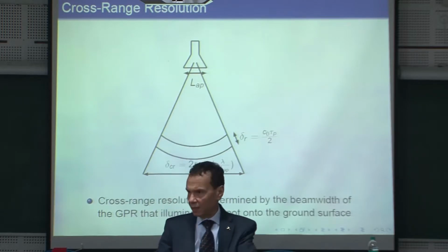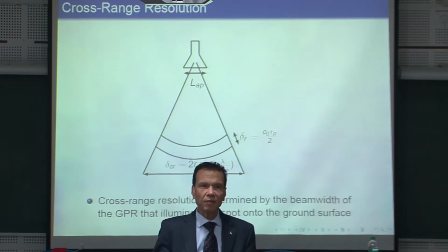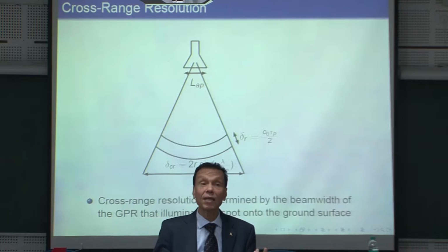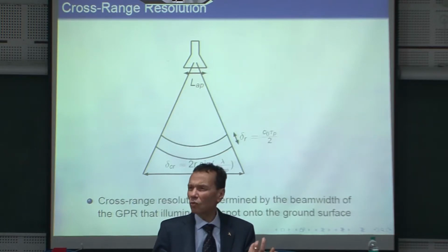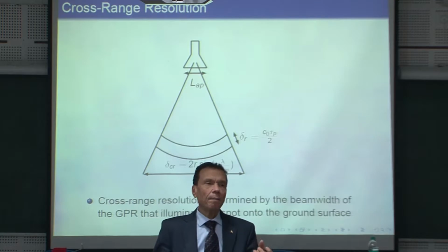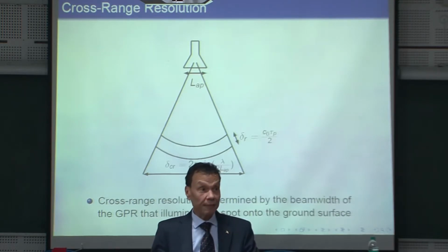Let me refresh your information: for the array factor, we assume that your unit antenna is isotropic, as if it were a point source or point receiver. But don't forget that you multiply the array factor by the unit pattern.